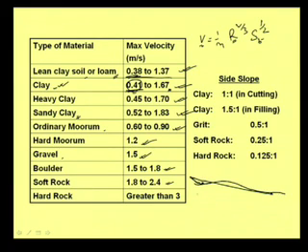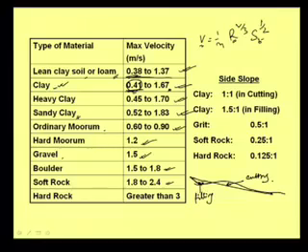Then we will fill up this portion and we will cut this portion. This portion is under cutting, and this material that we get by cutting can be filled up here to get the filling portion. Now definitely when we have a filling portion, the clay, although it is clay material, will be in a little loose state. Although we will try to compact it, still the in situ condition will have more strength than the filling condition.